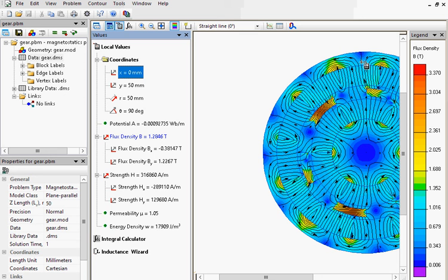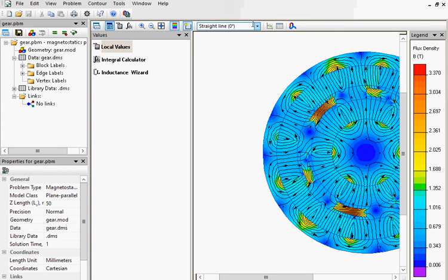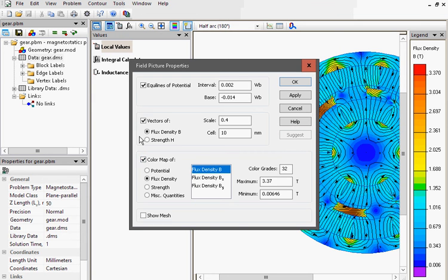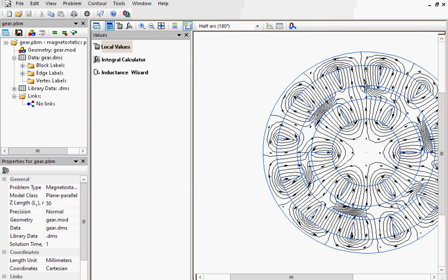You can also use contour tool to get the field distribution along the contour. Switch on the contour tool, change the line type to be the half arc. Before drawing the contour, I will switch off the color map so you can see the contour better. Okay, now click here in the A gap, drag, and then release.